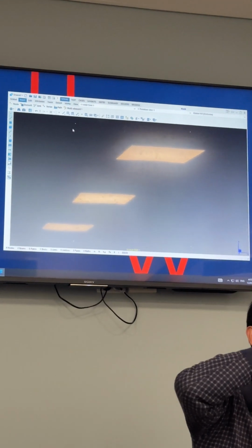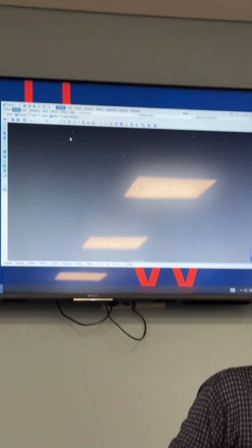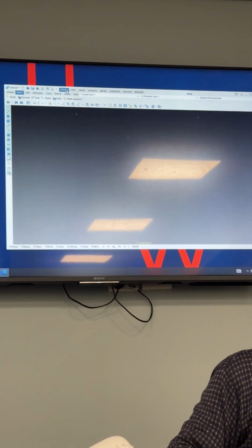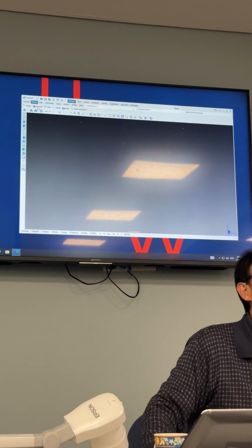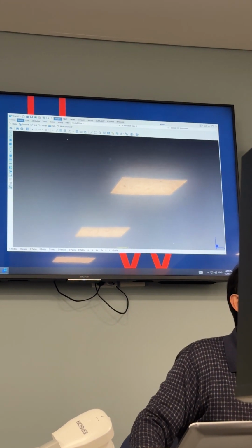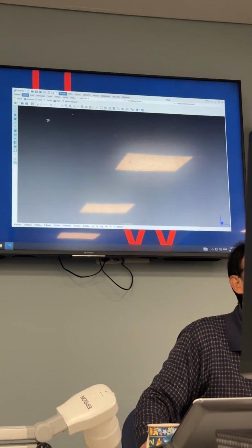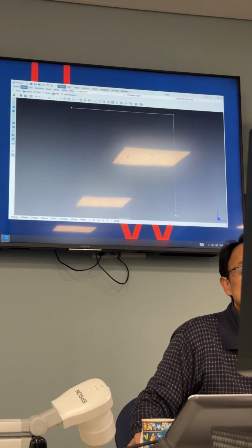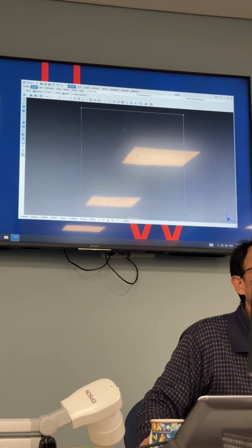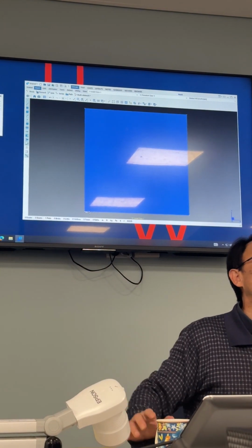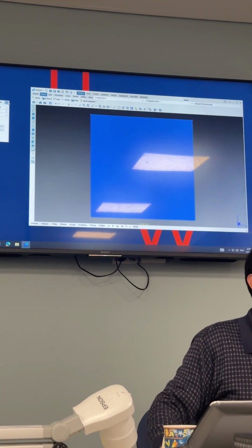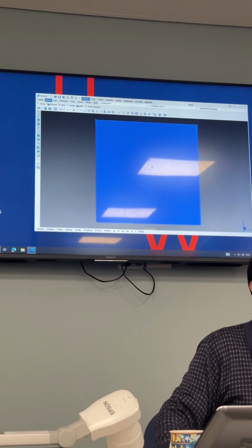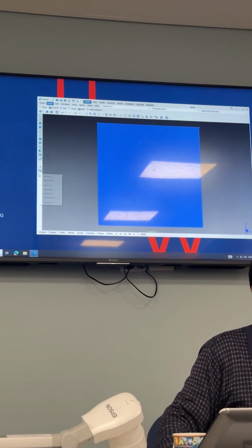When you imported the 4 nodal points, you're going to form a mesh: Visual, Insert, Element. The element you choose is quadrilateral 4, then you're going to find an element. This element has a dimension of 1 meter long and 1 meter wide. Move to here, right click.